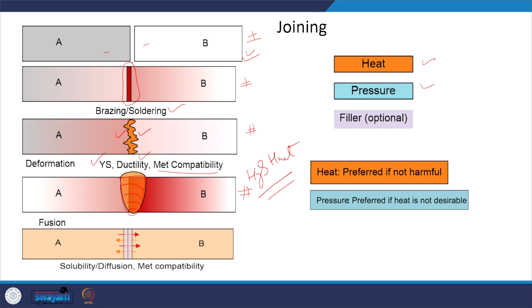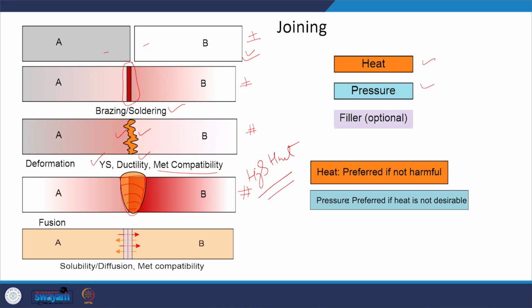There is one more approach that primarily involves diffusion across the interface of the two components to be joined, like diffusion bonding or diffusion joining. This also needs a reasonably high temperature, so that faster diffusion across the interface can take place in order to develop the joint at the interface.